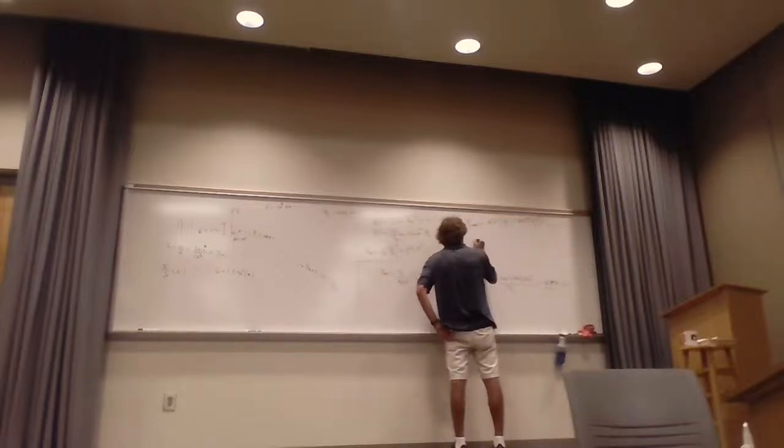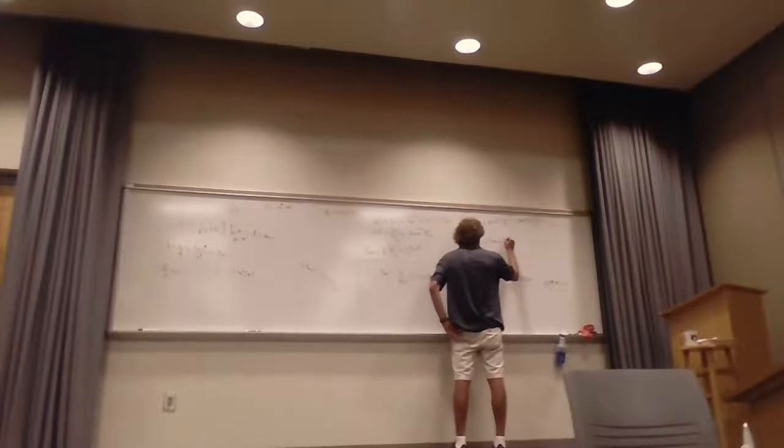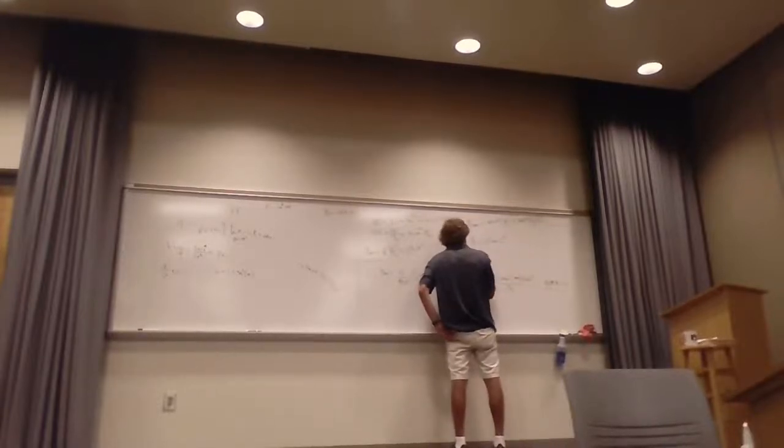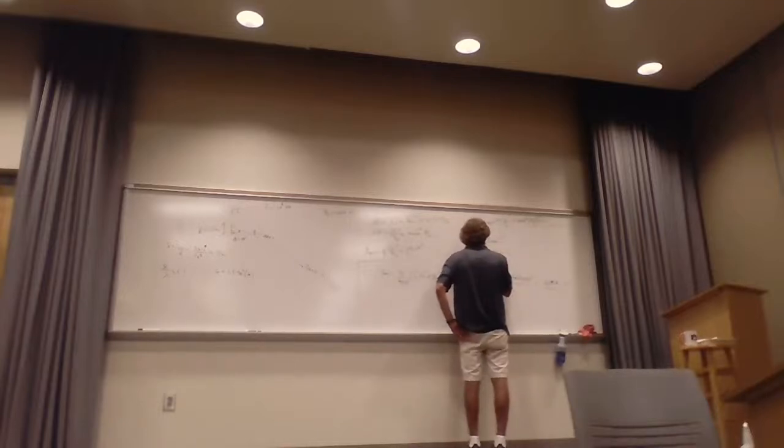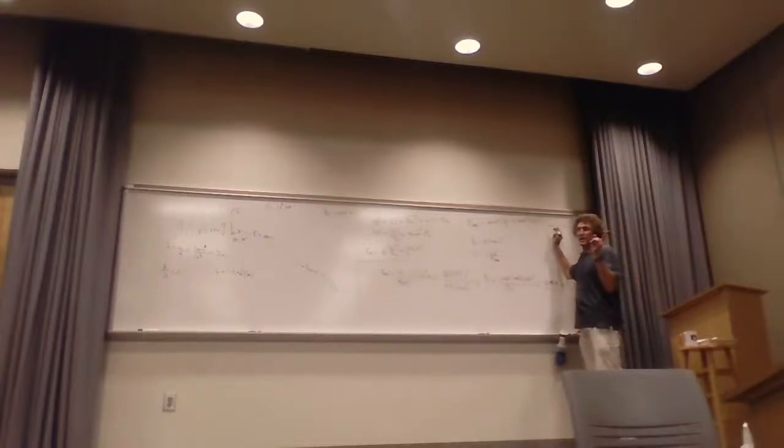And then you can say total power transmitted is 1/2 times R radiation times I squared. And therefore you can say that I itself would be the square root of 2 times P transmitted, total power transmitted, or P radiated, divided by R rad. And what was R rad? I'm sorry, the answers are up on OneNote, I just don't remember. R rad or P rad? The radiation resistance, because you're going to need that.